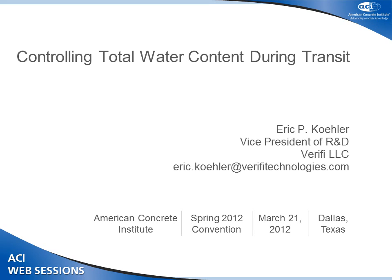So the company I work for, Verifi, makes equipment that, among other things, measures and controls the amount of water added during transit. So we have a lot of insight into how water gets added during transit, and I'll talk about that. So when we talk about total water, what we're talking about is water from all the different sources that are added to concrete, not just water that's added at the batch plant that's metered and known very precisely, but all the water that's in the truck.